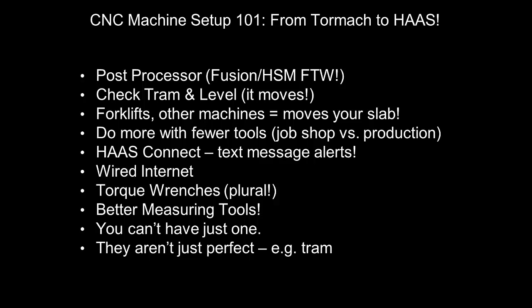We're considering trying to get ours re-leveled even after just 2 months, because I know it has moved a little on me. Two of my friends have bought high-end Japanese machines, and both have had some interesting problems with this stuff. One is more just temperature levels, the other is more slab related. So don't just assume you can plop down a machine with 40 inches of travel and have it make a 40-inch, perfectly square, perpendicular and flat part.